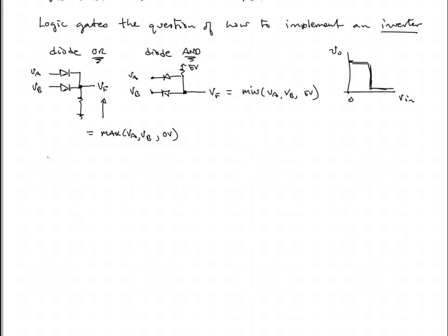Now let's consider a type of inverter. And we're going to start with something familiar. We will start with the voltage divider, a pair of resistors. And here, of course, the output voltage is going to be R1 over R1 plus R2 times 5 volts. And we could rewrite this and consider two cases for this resistance R1.